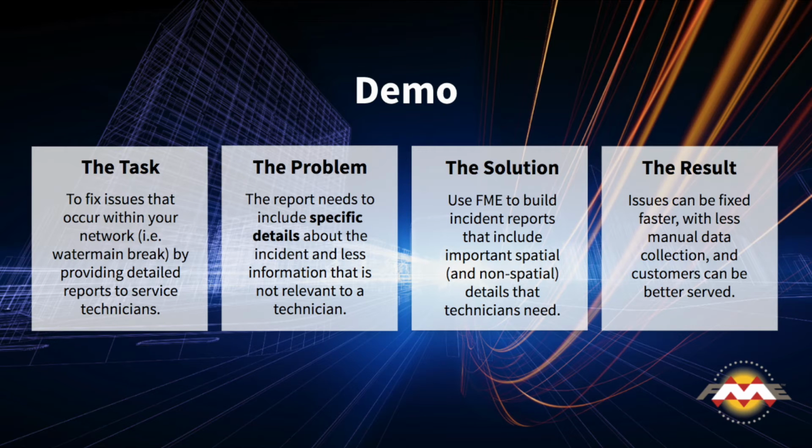that is reporting a water main break. Now, before any work can be done, we need to know a few things. Where did the break occur? How many addresses or properties are affected, as well as the number of properties at each residence that are affected. The time the break occurred if possible, because we want to know if people are without water, how long they have been without water. And then as well as the closest valve to the break. Now this is required in order to assist the technician to determine which valve they need to shut off prior to fixing the break.